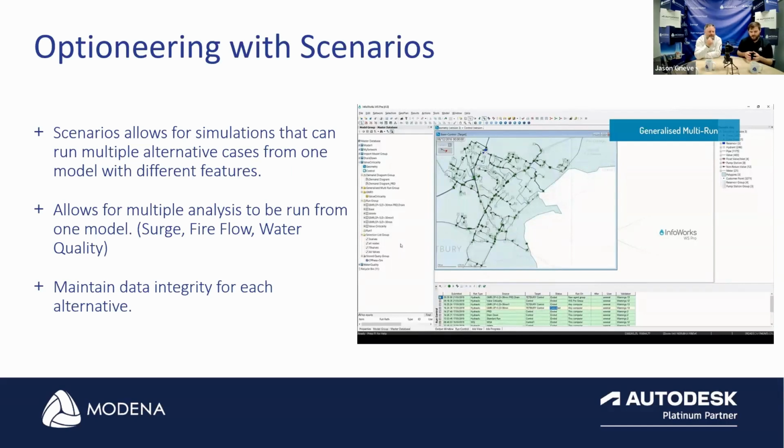And we can then take that same network and create different scenarios in which we want to analyze things like our surge or transient flows, our fire flow situations, and our water quality, because we can even track the stagnation of the movement of the water within the pipe. So we can make sure that if we have an area with slow movement throughout, that might be a system that needs to be flushed a little more regularly than what we do further north on the main line, anything like that.